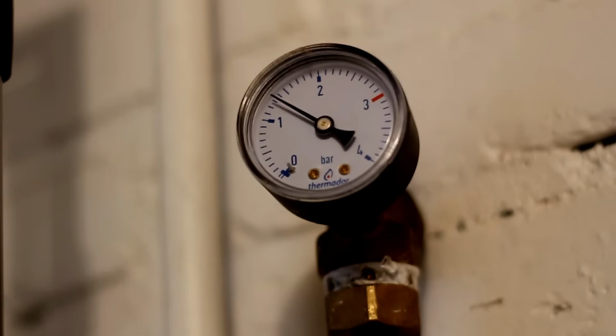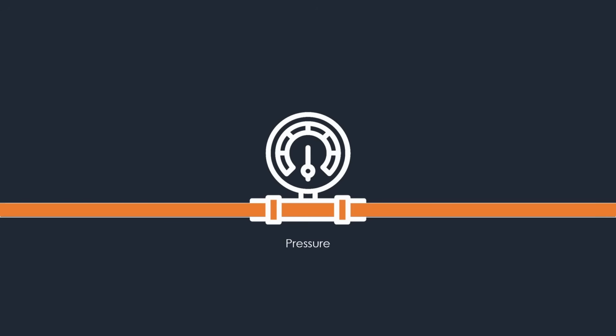That means a sensor doesn't have to always give an electrical signal. Even it doesn't have to be an electronic device. For example, take a pressure gauge. It measures the fluid pressure, air or liquid, and shows it directly on a dial. There's no electrical signal. Here it's purely mechanical, but still as per the definition, it's also a sensor because it converts a physical quantity, that is pressure, into a readable signal that can be interpreted.